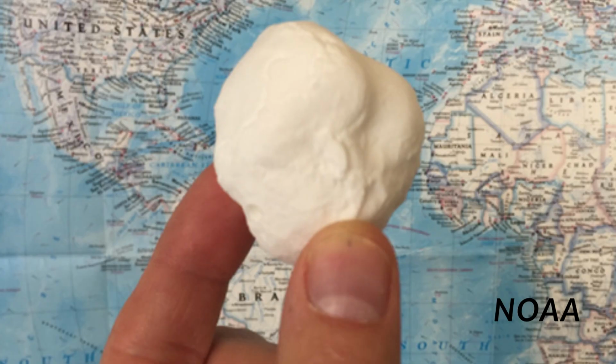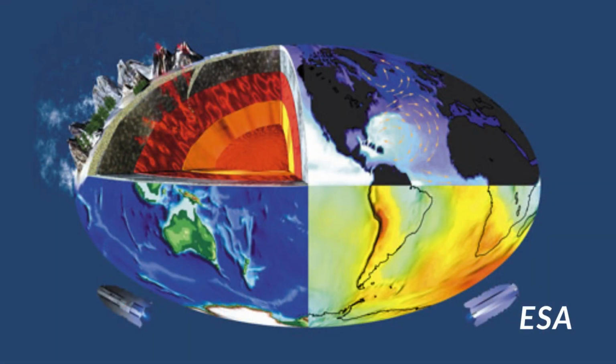Sure. Think about Iceland. There's a huge amount of dense volcanic mass there, which increases the local gravitational pull. Because more mass equals more gravity. Right. So in Iceland, the geoid actually bulges about 85 meters above the mathematical ellipsoid. Wow, 85 meters. And conversely, if you look at southern India, there is a massive mass deficit deep underground, causing the geoid to actually drop 106 meters below the ellipsoid.